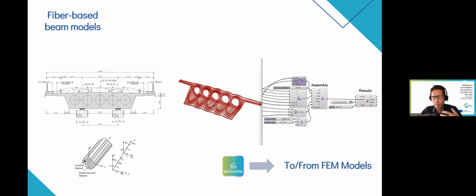But also, after the numerical simulations were embedded into the digital twin platform, they were not only those preliminary responses, but also more sophisticated responses to validate those models that were embedded into the digital twin platform, in this case for the La Plata Bridge, which represents a complex section with voids, and so we used, in this case, fiber-based BIM models.